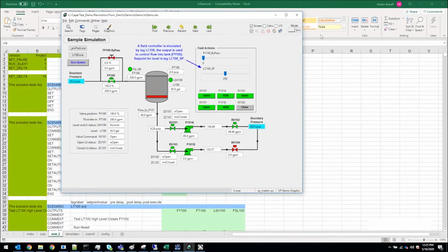We will now demonstrate some of the test compiler module features for VPLink. The test compiler allows for rigorous testing of a user's safety and control logic. It allows for multiple scenarios that test cause and effect matrices to be quickly set up and tested, while providing documentation that can be used for test verification and proof of compliance. Testing processes can be automated to ensure efficient testing, fault identification, subsequent rectification and retesting.